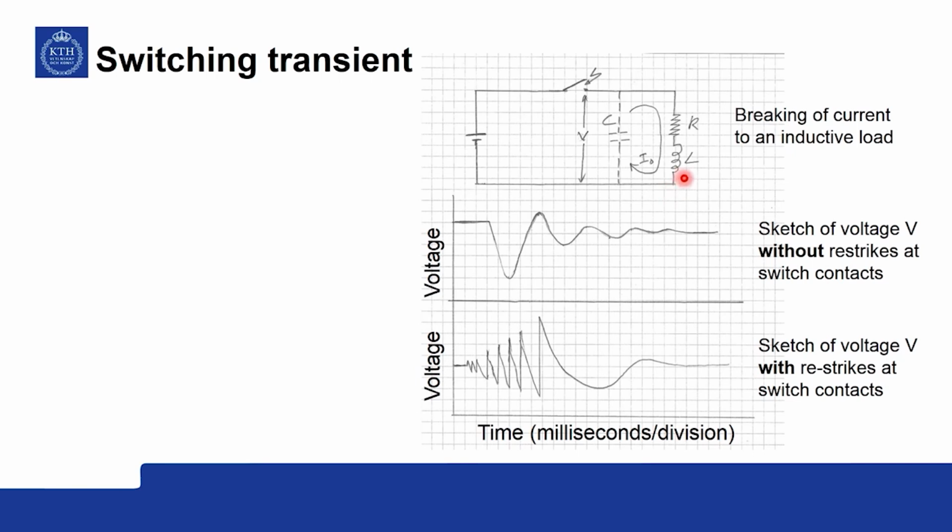So, this inductance of the load and parasitic capacitance together can form a resonating circuit. And this coupled with the breaking and closing of the switch can create noise.